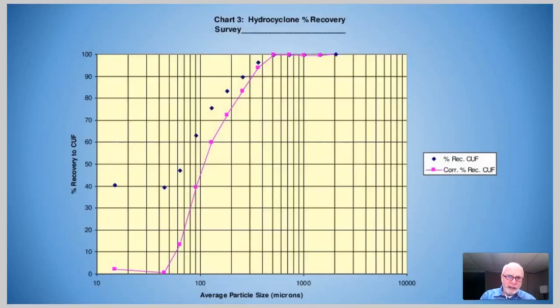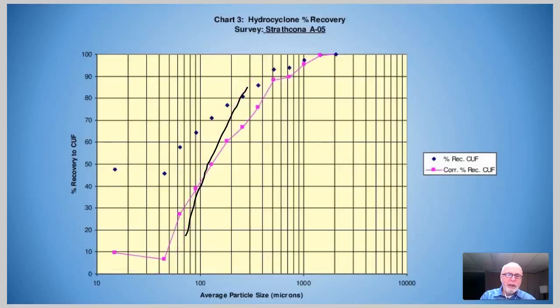And we can characterize the sharpness of separation by the slope of this curve, which I've just imposed in. And then if we compare it to an old style cyclone, we can see that we've got significantly improved separation sharpness with newer design cyclones. Now this contributes, at least in a small way, to improved CSE, a small positive way to CSE. So we want to take advantage of that.